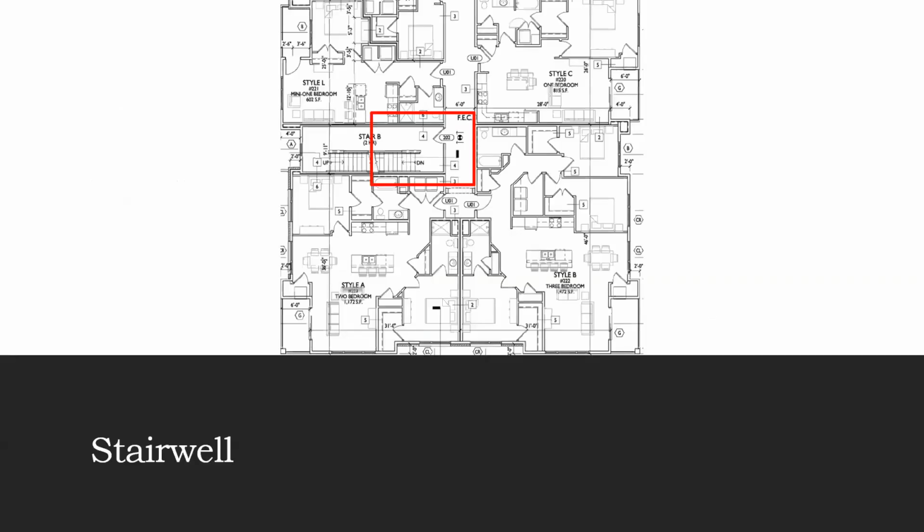So this is still in the code, but essentially in the past we saw a lot of doors protecting interior exit stairways and exit passageways that had temperature-rise cores. And again, it's still a requirement, but in the IBC 716.2.2.3, the exception is that it's not required in buildings equipped with an automatic sprinkler system. So with most buildings now having that, that's definitely going away and diminishing the need for that. But again, that stairwell is just another vertical penetration in a building, just like your elevator, and it does need to be protected.